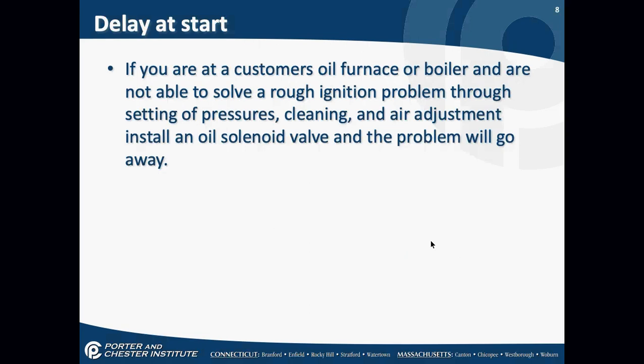If you're at a customer's oil furnace and are not able to solve a rough ignition problem through setting the pressures, cleaning, air adjustments, and making sure there's no leaks, install an oil solenoid valve and the problem goes away. A lot of the older equipment should have had this installed and the manufacturers didn't realize it. Or someone has changed a pump out over the last 50 years that had one of these installed and it was removed. So anytime you have a rough ignition, and you can hear it once you get used to it, and you've cleaned and adjusted everything, throw in an oil solenoid valve and the problem goes away.